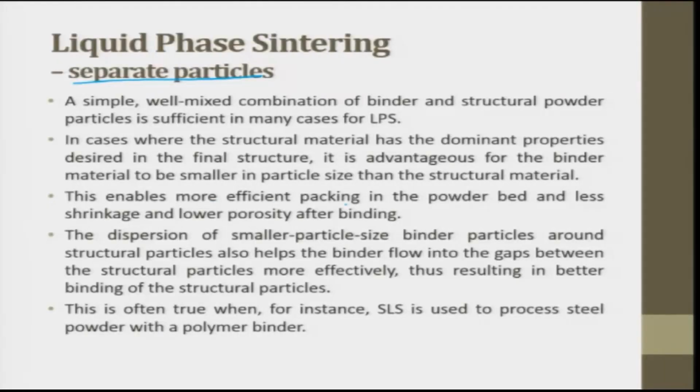for cutting tool application. This enables more efficient packing in the powder bed and less shrinkage and lower porosity after binding. So this enables more efficient packing because the binder size is very small. And less shrinkage, because the particle which is going to melt and flow only later shrinks. So now that shrinking has gone very low, and the lower porosity after binding, because wherever there is a pore it will get filled up.